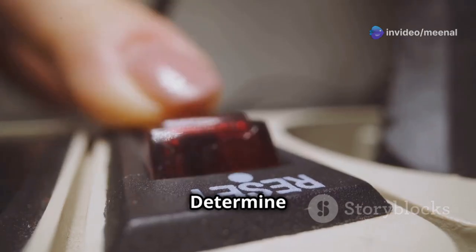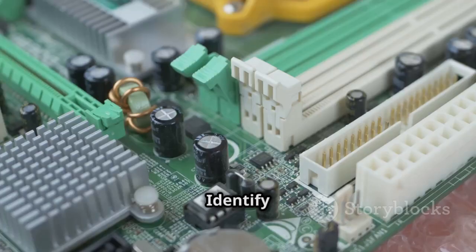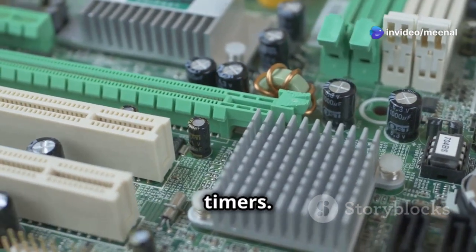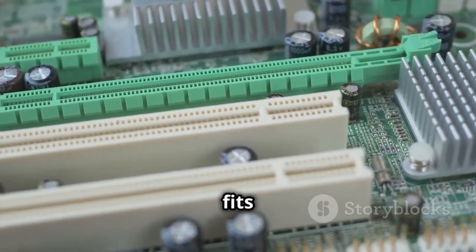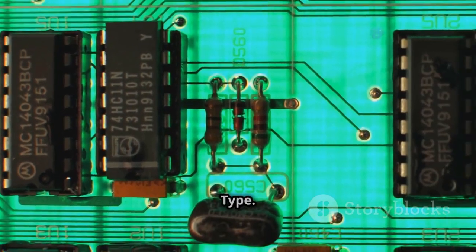Step 1. Determine reset source. This is the foundation of your reset circuit design. Identify the source that will trigger the reset signal, such as power on reset, manual reset buttons, or watchdog timers. Each source has its own unique characteristics and applications, so it's important to choose the one that best fits your device's needs.